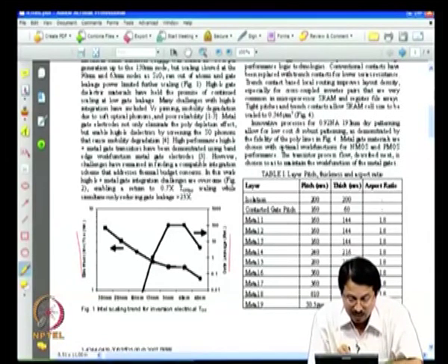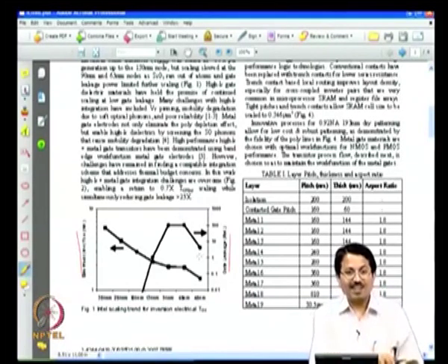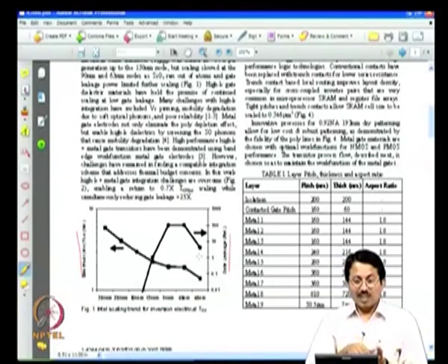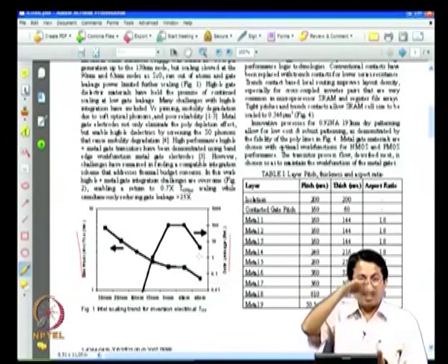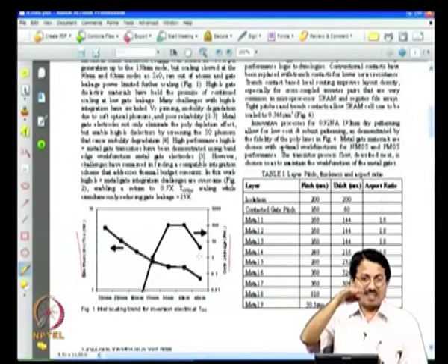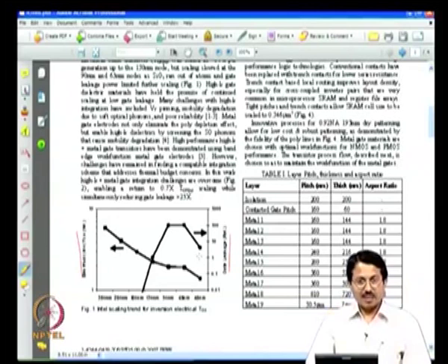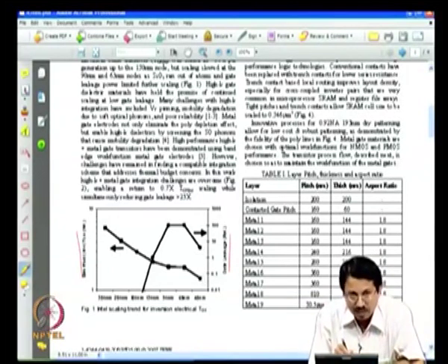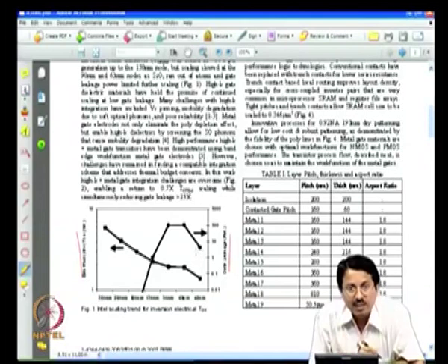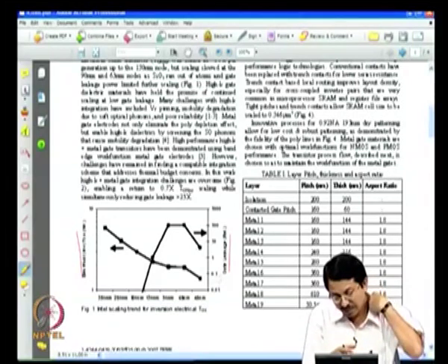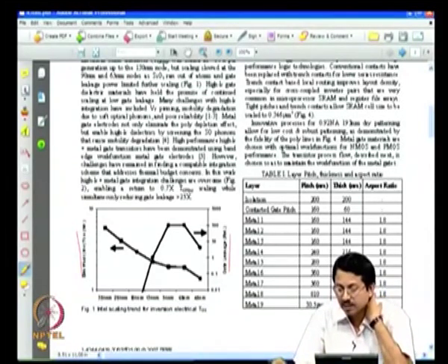Now with the high K technology the EOT came down, but the leakage did not increase, the leakage also came down, because it is an EOT of 1 nanometer, but indeed it is a thicker physical oxide, direct tunneling is suppressed, and hence you got the best of both worlds, you got lower EOT and lower leakage current. That is why you want to use high K gate dielectric. That is illustrated very nicely here, showing the trends in different technologies. So, this is a high K, and metal gate is different for NMOS and PMOS.